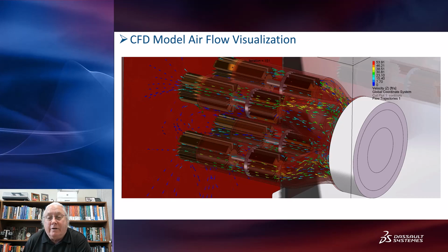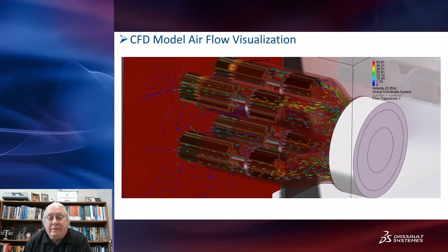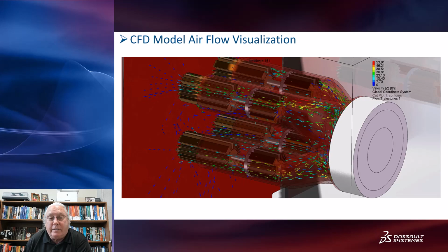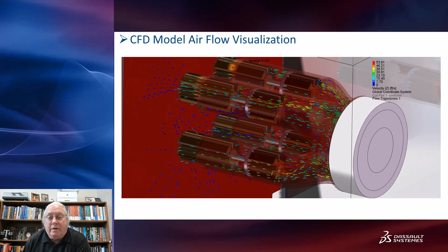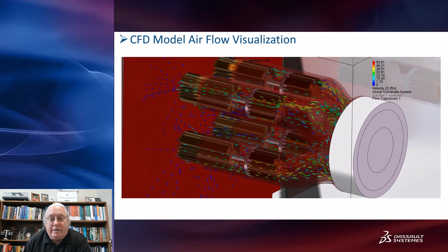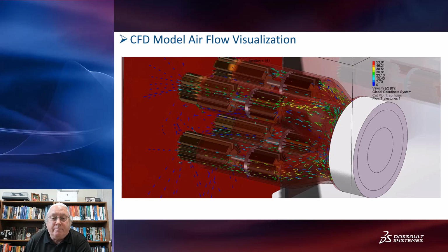But this helped me design these air ducts to get the air flowing directly across those heat sinks. So that helped. We used this simulation to help optimize the configuration, the geometry of those air ducts as we went through the design.